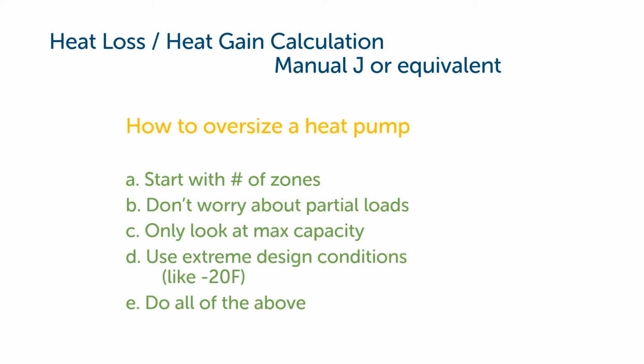Don't start with the number of zones that you need to satisfy with a multi-zone heat pump and just put a mini split head in every room. Don't worry about partial loads. If you only design for design loads, we're not going to have a system that runs steady and can modulate down to the lower loads we need for most of the heating season. We have to look at the max and the minimum capacity.